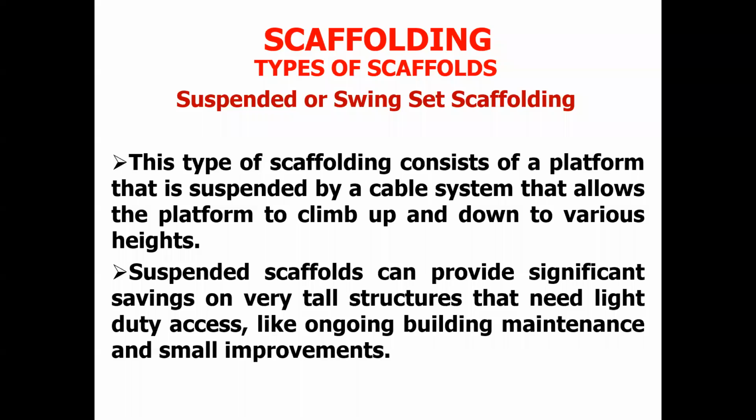Usually this cleaning cradle might have something like a boom. And this boom is what sticks out. And then cable drops from that boom. And on that cable is supporting a platform, a car. So this system moves up and down the facade of that particular building to be able to clean that curtain wall. I'm sure that you might have seen it somewhere, even in movies. I'm sure you must have seen something like that. So that system, that is what we call suspended or swing set scaffolding.